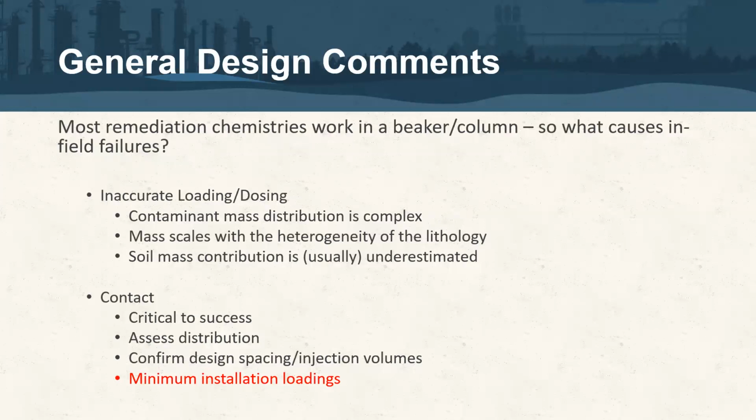And by that, I mean, despite doing your bench scale evaluation, coming up with a loading that matches your mass flux or your source zone concentrations of PFAS, we find that from a distribution and contact standpoint, which is essential with any reactant reagent product you're installing in situ, we found to date about half of these require the minimum installation loading. And so the best way to explain that, if you haven't dealt with us on minimal installation loadings, is think of it as the proverbial drop of blood in an Olympic-sized swimming pool, right, with the shark.